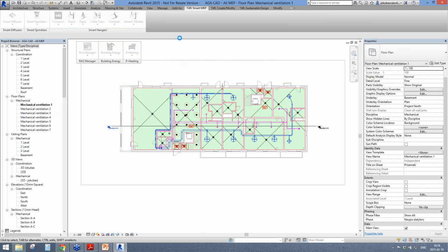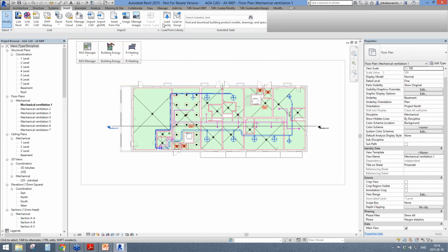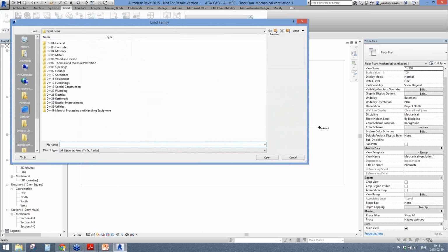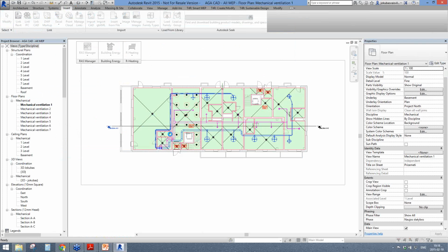So I will turn on this dialog block, and I will go simply to the Revit insert tools, and I will load the families. You can imagine that we have saved the TXT file that becomes the RFA family type of the radiator. Just in a second, you will see a dialog block where we can find all the needed radiators. We can insert these families into our project, and these families will have all needed parameters like the flow, the pressure drop, and many more things here.